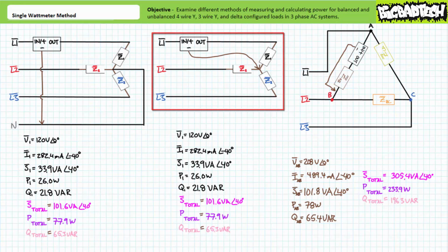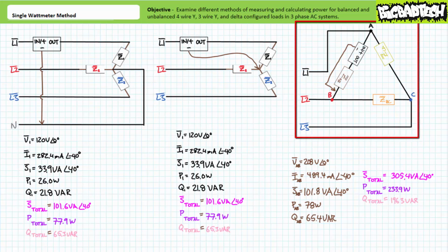Directly measuring voltage is. Balanced delta configurations present a similar disadvantage, only with respect to current measurement. Note the voltmeter portion of the wattmeter is directly measuring voltage from an externally accessible line to another externally accessible line, A to B. The ammeter portion of the wattmeter is, however, measuring current through a load buried deep inside the delta configuration. Oftentimes, the delta configuration is fixed and inaccessible, the classic example again being a 3-phase AC delta configured motor, where the 3 points of the delta configuration of balanced windings are externally accessible, however the configuration cannot be broken to incorporate an ammeter in series.